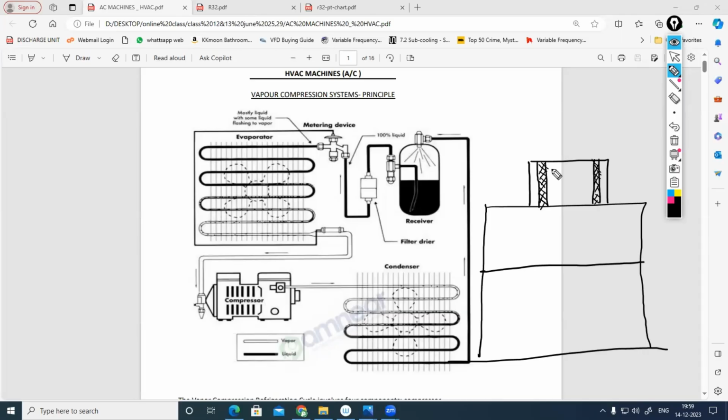That has 99.997% filtration efficiency. But a filter with 99.999% filtration efficiency is called a ULPA filter. The filtration class we can discuss, but the conventional filter that we use in the residential wall mounted split AC is a throwaway filter or washable filter. It is not in a position to isolate bacteria and all. It can isolate only dust. Okay, in the filter class we can discuss. I'm not wasting time. These are the filters that can come.